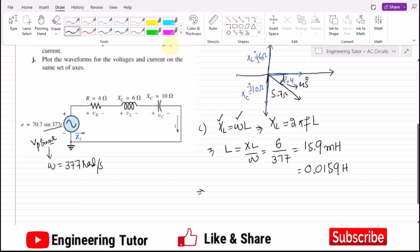Similarly, in order to find the value of C, we know that X of C is 1 over omega C, or the value of C is 1 over omega X of C. Putting their values here, omega is 377 and the value of X is 10. So this would be 1 over 3770.